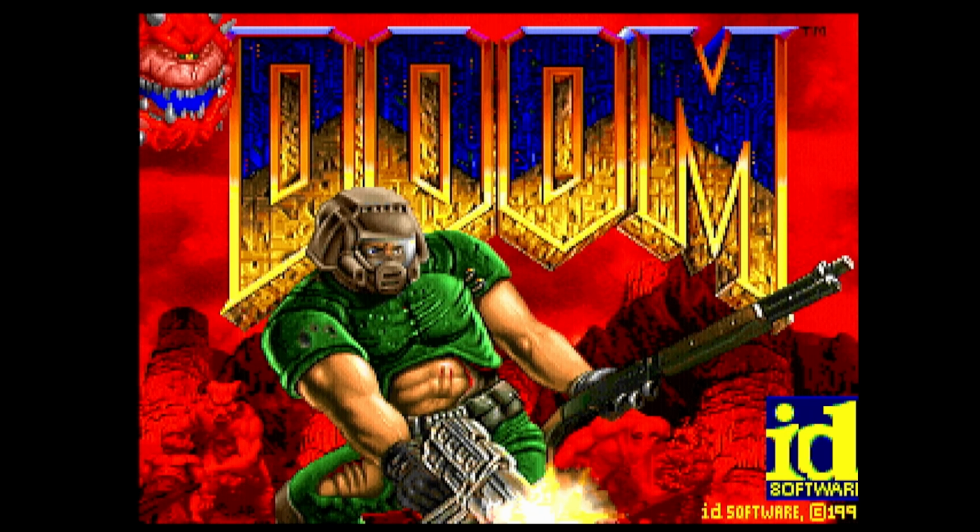Obviously, what this does indicate is that updating high resolution graphics screens without having this sort of interference is quite a challenge, and really in later video cards, dual ported video RAM and much more sophisticated circuitry was used to avoid these sort of screen artifacts. So the high color mode is possible to get working. If I had the serial communications handshaking working a bit better, we could probably get this working a bit faster, but I was really just trying to indicate how to stop the screen update snow.